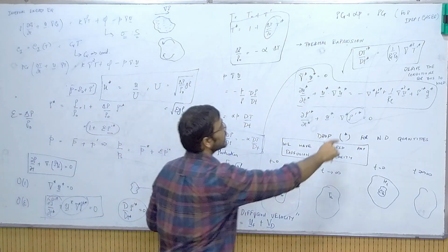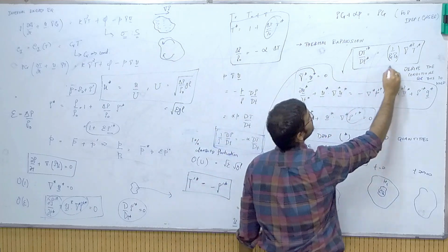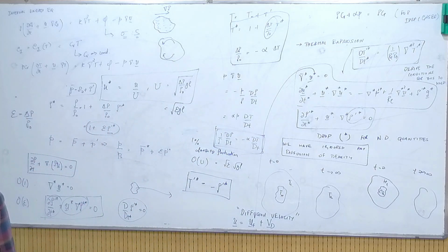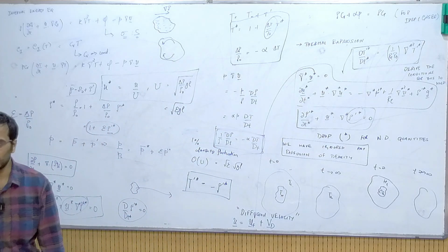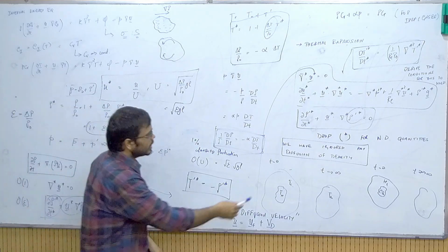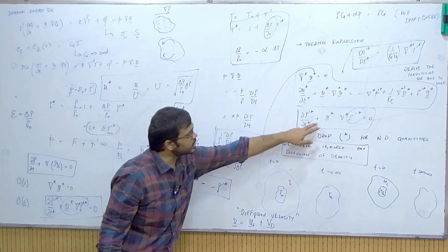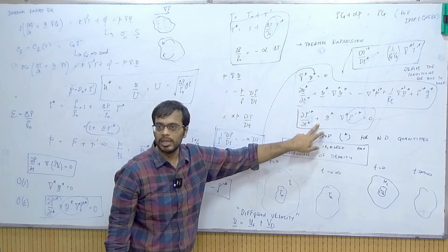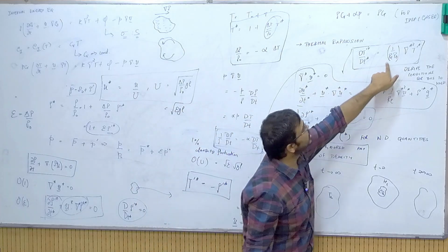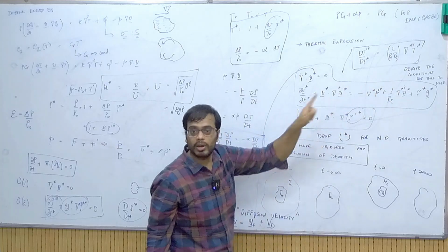When you substitute that here, you will see that this equation and this equation will not be the same. They will be contradictory. You will have two different equations in rho prime star, and the reconciliation is the velocity due to diffusion of density. In our derivation of this equation, we have ignored that velocity, but there needs to be a diffusion velocity that you account for, which accounts for this diffusion of temperature or diffusion of density.